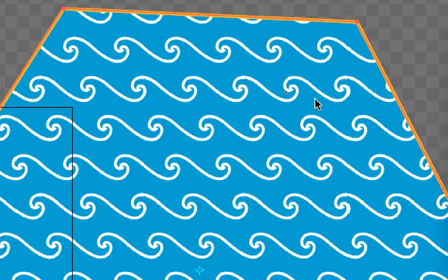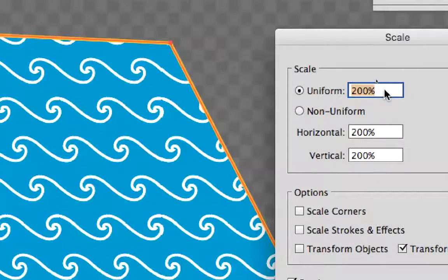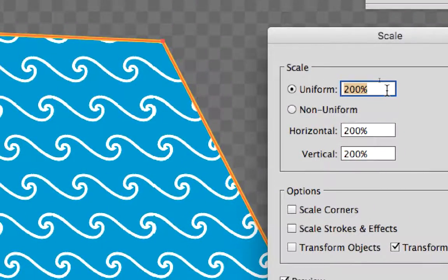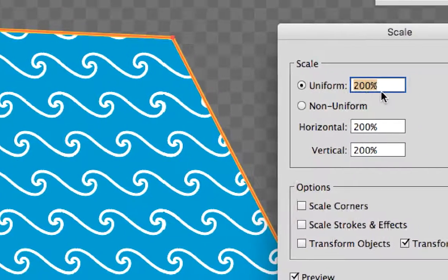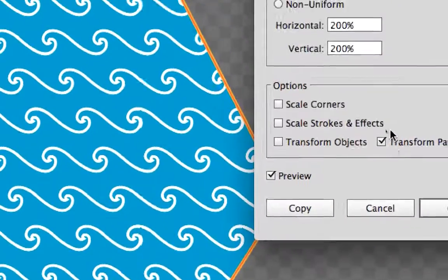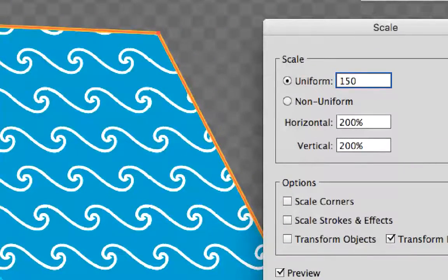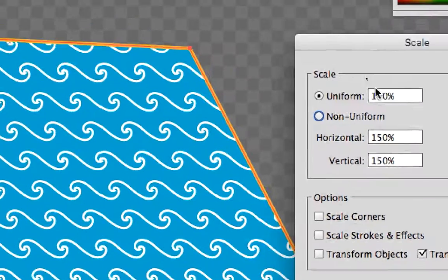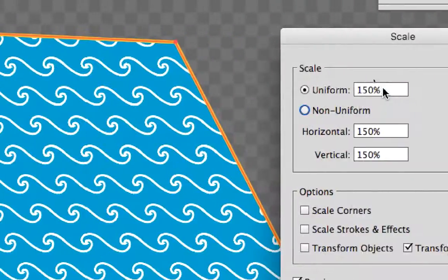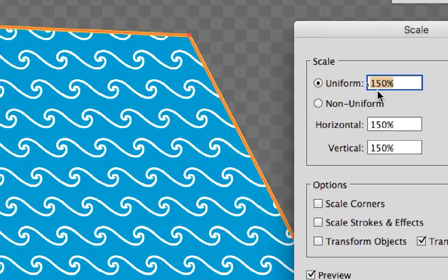So now it is 400% compared to its original size. So be aware of this feature. When you come back in the scale panel, your earlier settings come back. So maybe I make it 150 here. Tab. Okay. So you must watch what happens on the shape in order to choose the right setting here, of course.